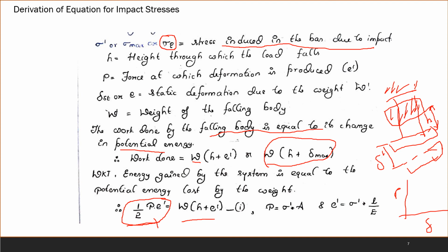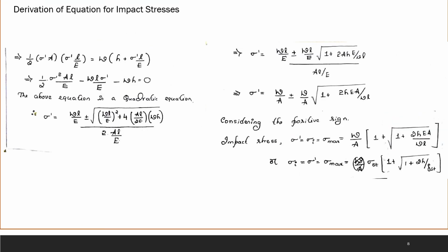Now we know that force is equal to stress into area, and deformation is equal to stress into L by E. Substituting that and equating both, we will get a quadratic equation.